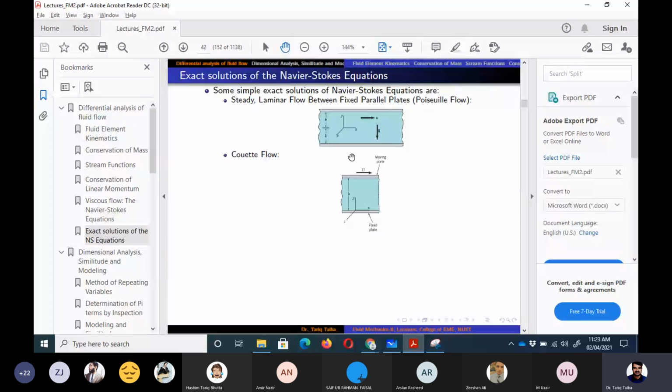the flow of some oil or grease in a ball bearing. In that ball bearing the upper part is moving. So that is circular, but we can always break it and spread it out in the form of a flat plate, right? And then we have steady laminar flow in a circular tube, and then steady axial laminar flow in an annulus. Annular means that we have two concentric pipes, and there is a flow in the space between the outer pipe and inner pipe, right?